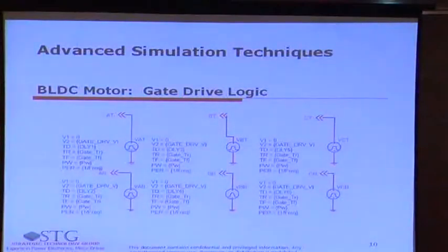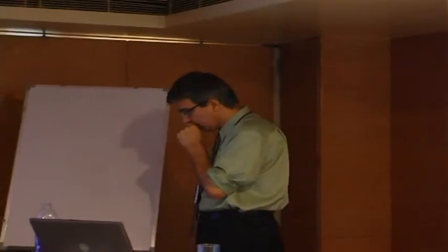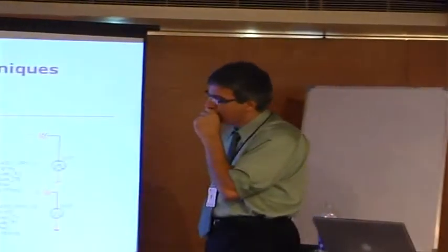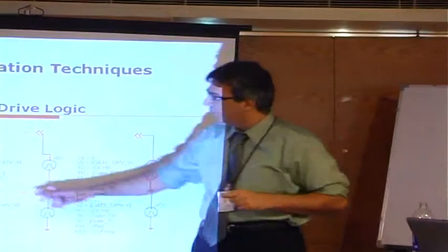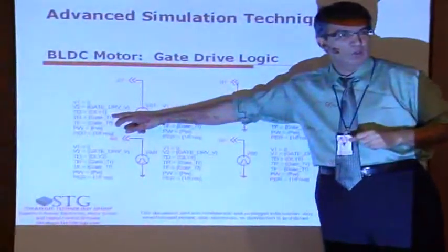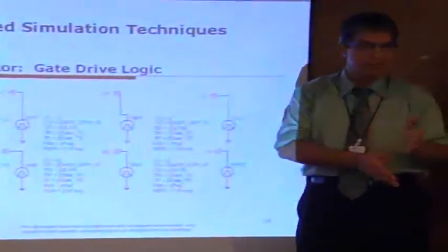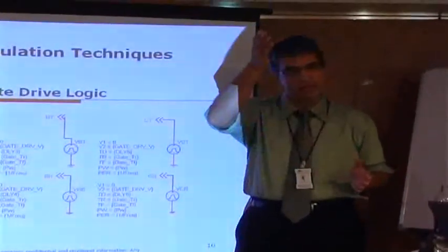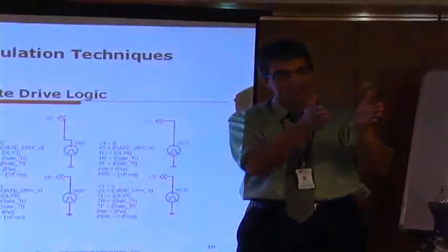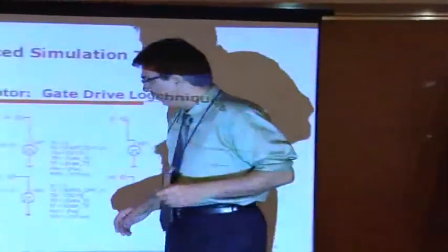Any questions on this one? Are these delays entered one by one, or are they computed automatically somewhere? We set the first delay, and the rest is computed automatically. Delay 1 would be 0 if you were starting with the PWM when the back EMF was rising, right? But you have a 30-degree delay between.